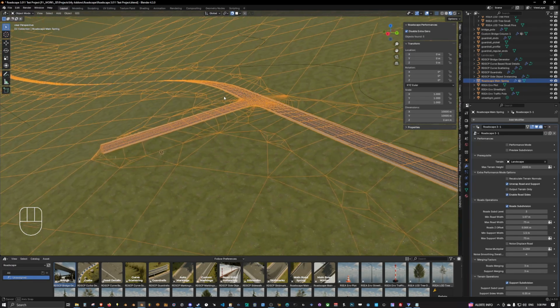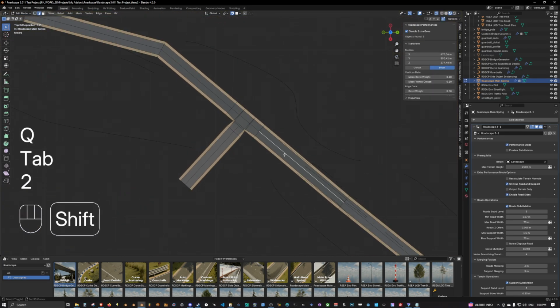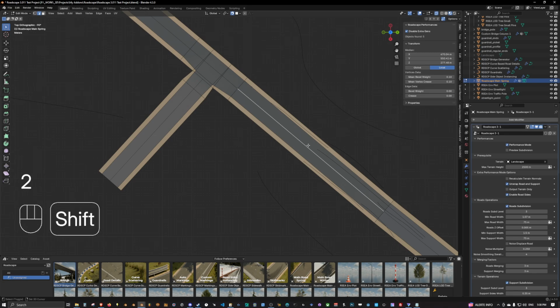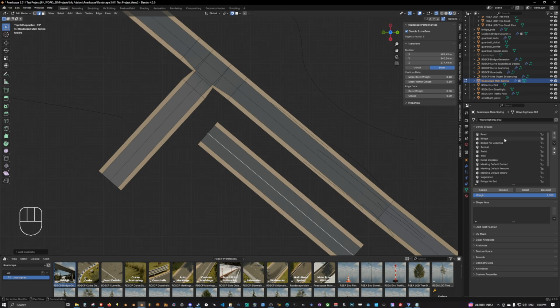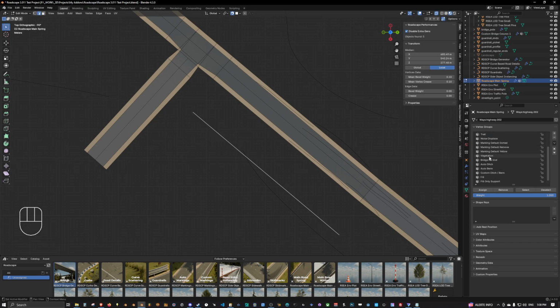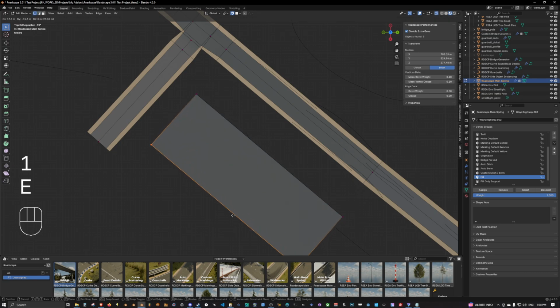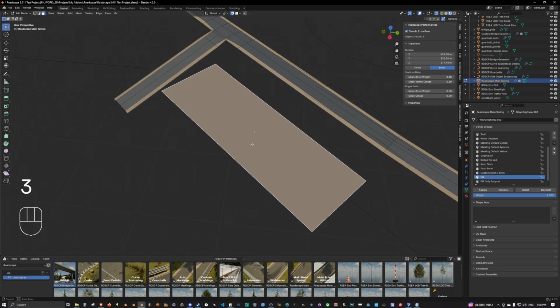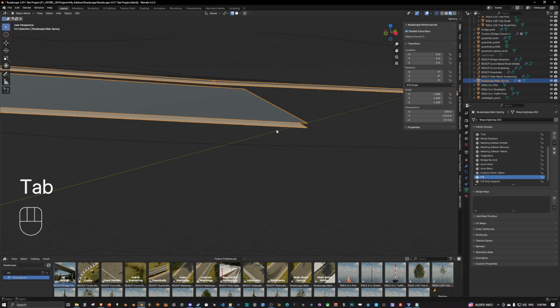And we are going to go with the new fill mode. So let's go back into performance mode, and then we are going to simply duplicate this edge, and then we are going to go into vertex mode, and we are going to remove road from this edge, and we are going to add fill. Okay, and so we have added fill to this edge. We can simply hit E and extrude. Okay, then we have now a fill face, which is a fill road face and a fill support face.